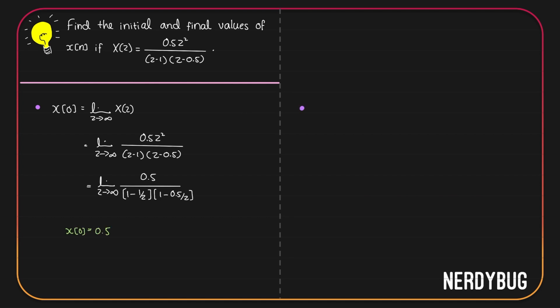Again, according to the final value theorem, x of infinity is the limit as z tends to 1 of z minus 1 multiplied by X of z. So it will become the limit as z tends to 1 of z minus 1 multiplied by 0.5 z square divided by z minus 1 multiplied by z minus 0.5.